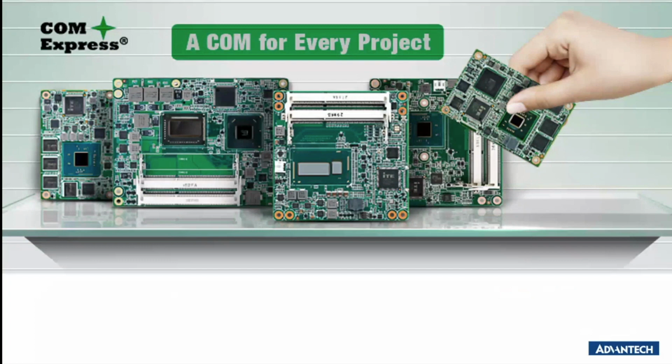Now, the last few slides. Next is about COM Express, computer on module. In short, COM Express, like I mentioned, is basically a CPU module that comes with RAM and all the necessary things like gigabit LAN or maybe audio. All the major controllers are on this CPU module, so this is the heavy lifting. Most of the items are on this board. You just need to build a carrier board to pull out the signals.